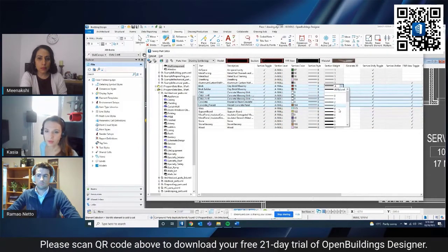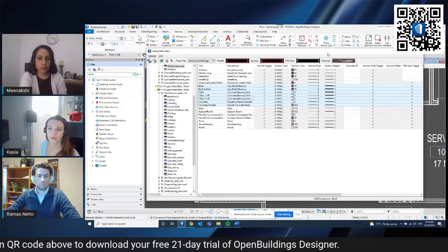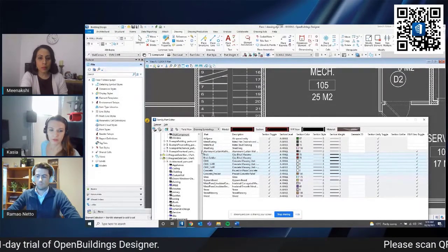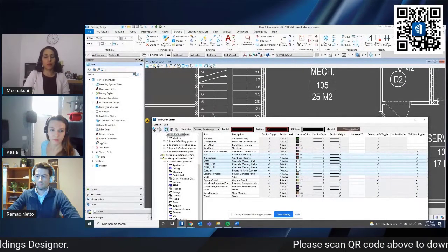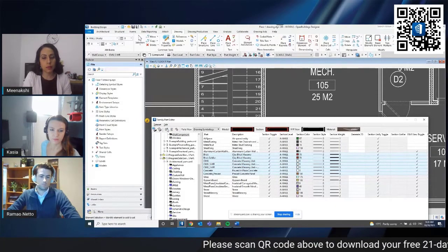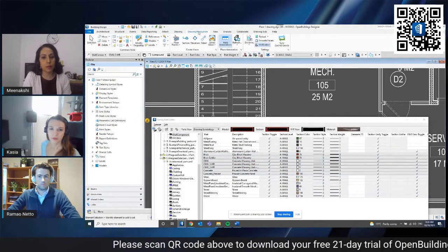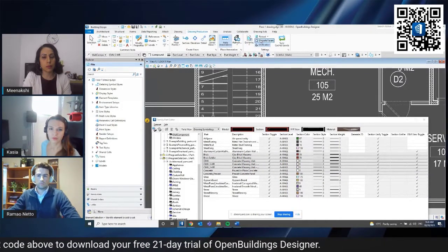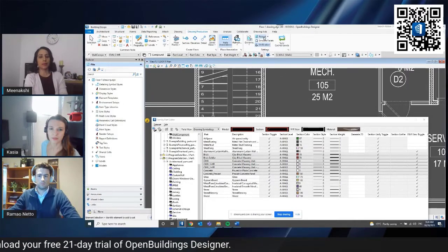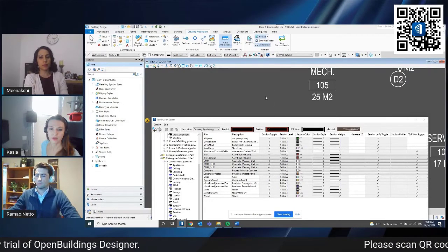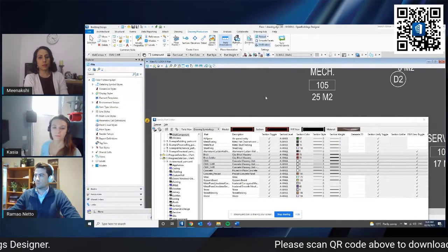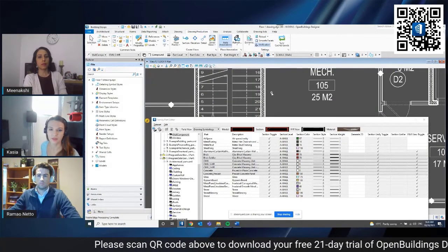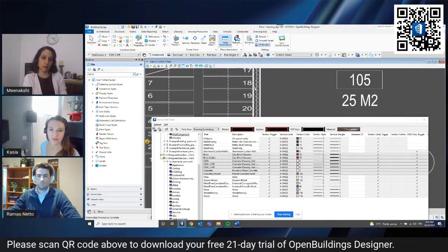Or let's make it even bigger to see the difference in the drawing. So once I have it modified, I can commit the changes here, and then in the drawing production tab, I can reload my drawing in this settings section, and you will be able to see the difference in the line thickness. So it's much thicker now. I think you can see it. And still we have this crosshatch.